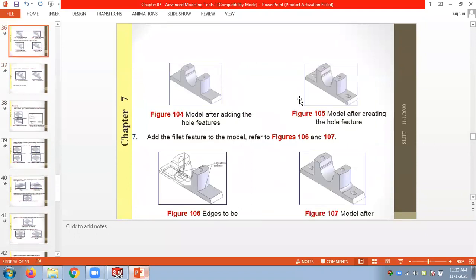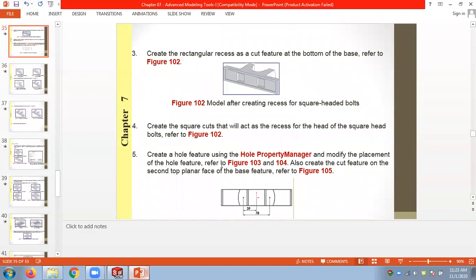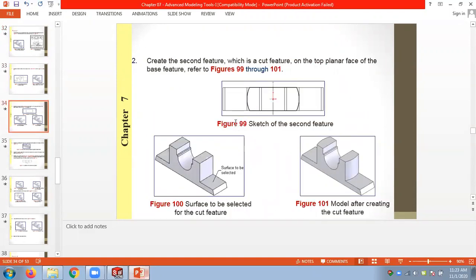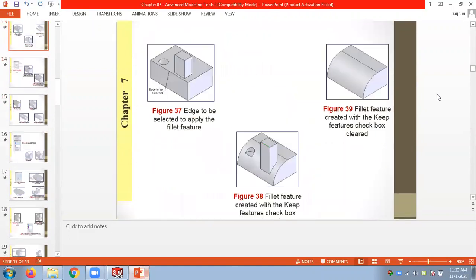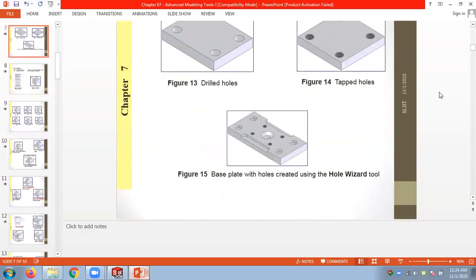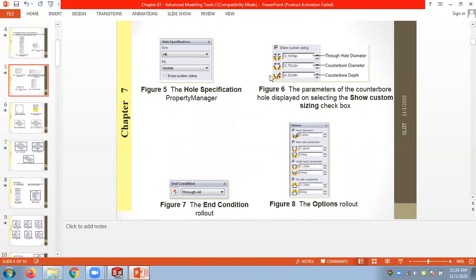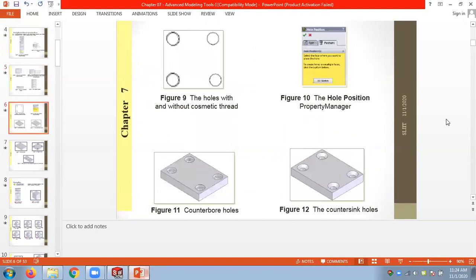here we are using these standard holes. So when I do the tutorials, these are standard holes. We will use them as it moves on. So I hope you understood how to work on the advanced hole, sorry, hole wizard and the simple hole. So all these parameters you need to either look at from design books and change them, and according to your calculations you have to do it.